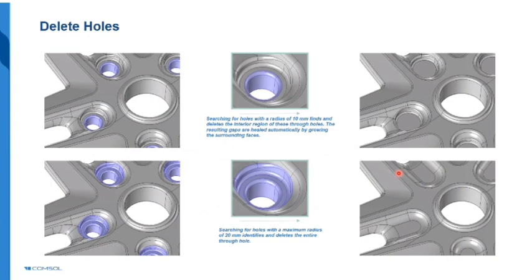Then for the imported geometry, there are certain other options. Again, these are about how you can improve your CAD for further modeling, because we do not want unnecessary details in your CAD, which will lead to extra mesh elements and extra surfaces, because of which your model becomes unnecessarily heavy.